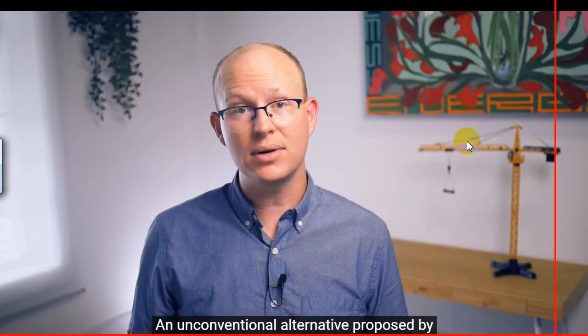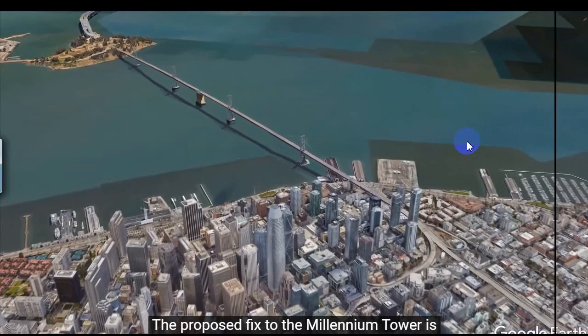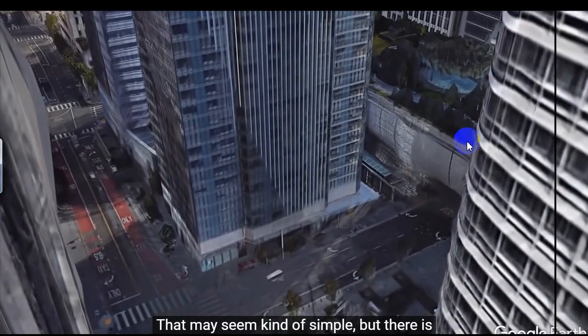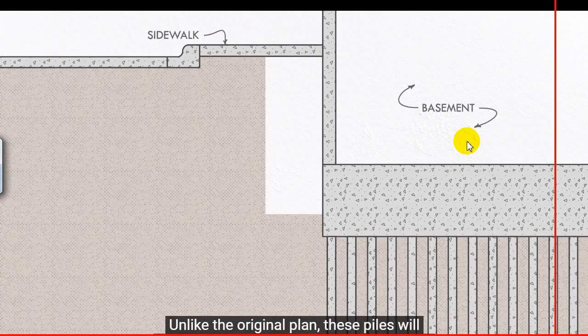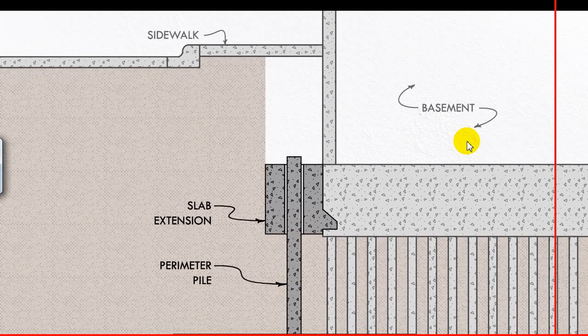An unconventional alternative proposed by the developer's engineer ended up resolving the dispute, and as of this writing, is currently under construction. The proposed fix to the Millennium Tower is to install piles along 2 sides of the building's perimeter. That may seem kind of simple, but there's a lot of clever engineering involved to make it work. 52 piles will be drilled along the north and west sides of the tower, all the way down to bedrock. Unlike the original plan, these piles will be installed outside the building below the adjacent sidewalks, saving a significant amount on the construction cost. An extension to the building's existing concrete slab will be installed around each pile, but not rigidly attached to them.